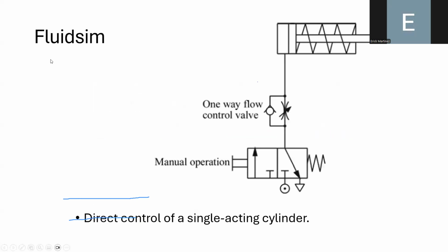And well, this is like a diagram, no? So in the following video, I will explain how you can simulate this pneumatic circuit in FluidSIM. But let's first analyze what is happening in this pneumatic diagram. Here you can see that we have a button. Okay, so this button basically means that in order to switch to this position, you need to push this button.